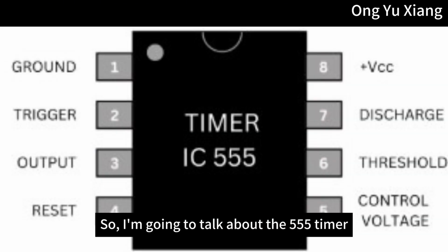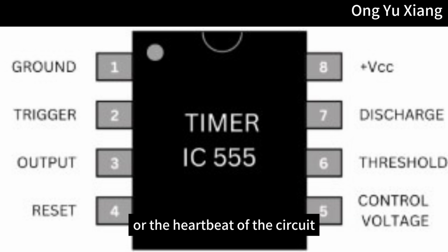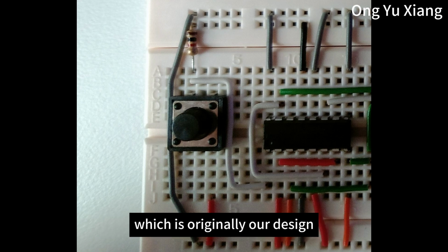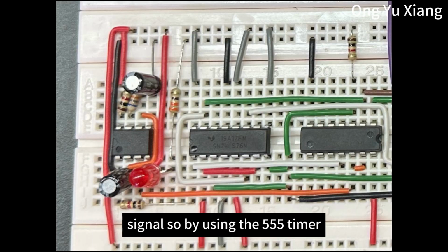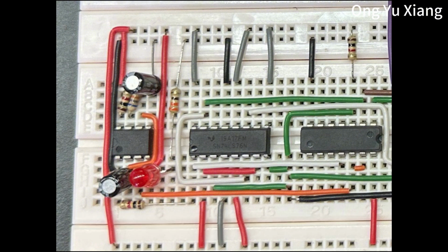So I'm going to talk about the 555 timer in our circuit. The 555 timer acts as the astable multivibrator, or the heartbeat of the circuit. Its job is to generate a continuous square wave clock pulse. This replaced the manual push button, which was originally our design, because the push button is unstable and often bounces the signal. So by using the 555 timer, it ensures a consistent and bounce-free signal to trigger the JK flip-flop.